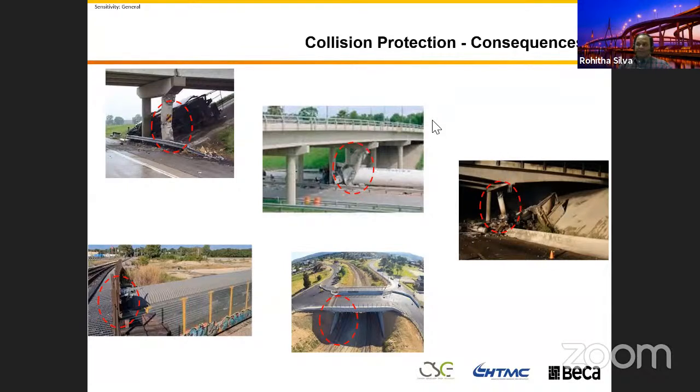On top of that, you can't let the traffic be on the bridge because it's not serviceable. So therefore, when you design a bridge going across the highway or railway, you have to make sure that the columns located close to your highway are protected. Yeah, you have to protect. To do this, there's a very lengthy risk assessment procedure. We can do this one.